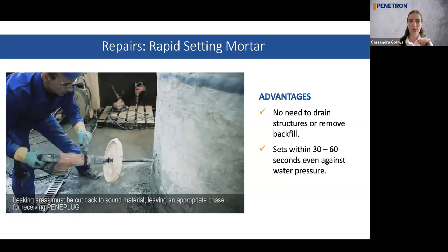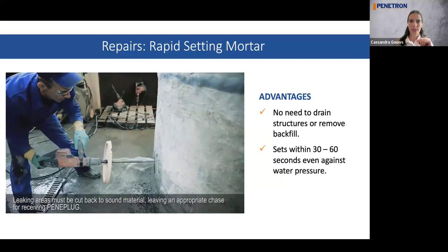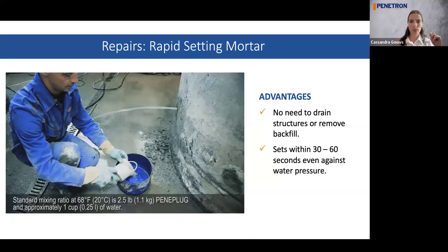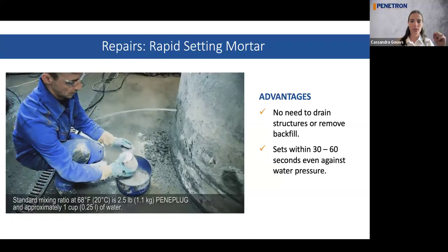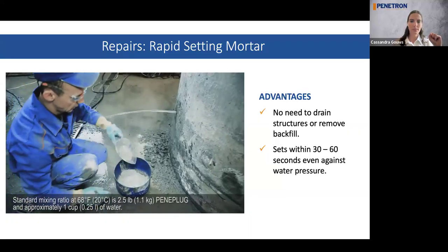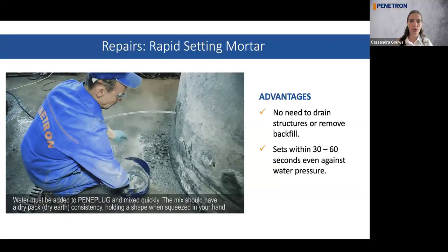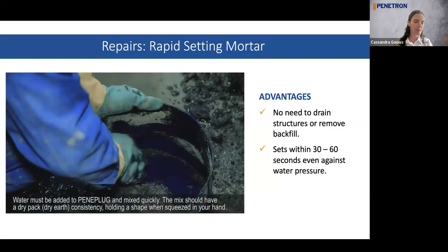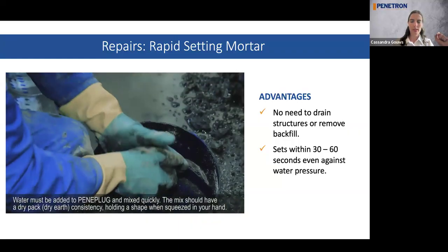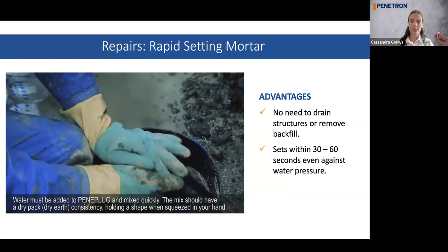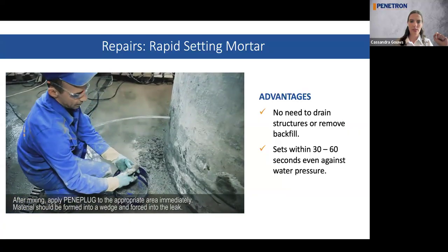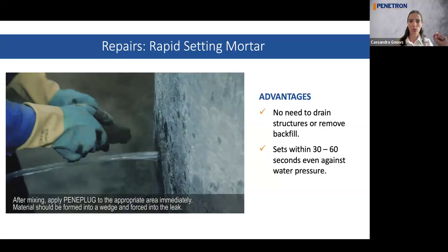They're prepping the hole. And then they take the rapid setting mortar. It's like a hydraulic cement, but it contains the crystalline technology in it. They add very, very little water. They mix it into quite a dry pack consistency. And then they literally plug the hole, right?